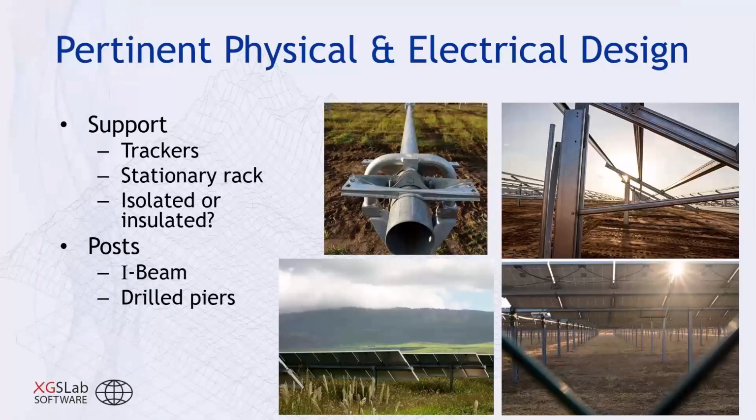Other pertinent physical details to be aware of is what the posts are. It could be an I-beam, it could be a drilled pier, and in some sites, they may be installed in areas that have relatively high resistivity, or if it's installed in relatively low resistivity, then there's concerns about corrosion occurring. And if there are those concerns, they may use a post that is coated so that it's protected from that corrosion.